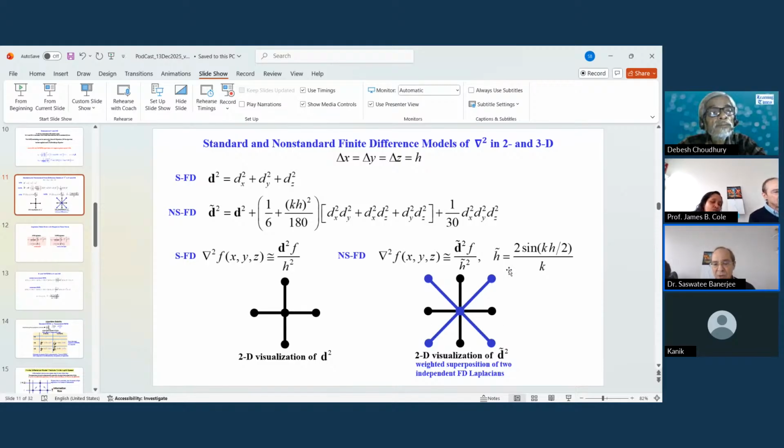Here, we've adjusted. This is where the superposition comes through. This superposition here is what makes this more isotropic. We're using these diagonal points. So we've adjusted the superposition parameters such that the diagonal wave speed is the same as the left-right wave speed. And this makes it much more isotropic, and then it makes it much more accurate.